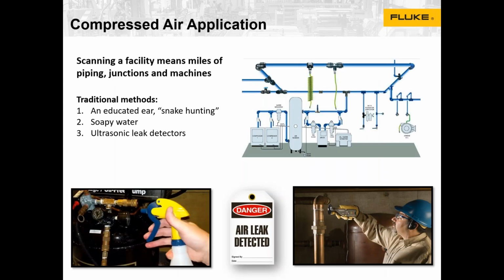As I mentioned, the primary application that the tool was developed for was compressed air. Our customers were telling us, hey, there's a lot of opportunity to improve on the way that this is done. We heard customers telling us that they would do something called snake hunting, or when they had a planned shutdown, they would send a team of folks around, literally walking their entire compressed air infrastructure, listening for hisses. And obviously this couldn't be done while production was running because of the ambient noise.